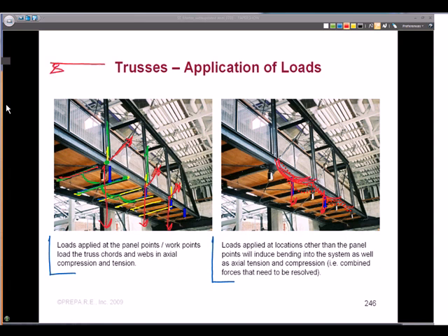Well, we could probably simplify it. It's just a point load in the middle. And the span, we could find that very quickly, right? M max from our loading diagrams equals PL over 4. Okay, now you'd have to calculate it, but that would be the approach. This is just a simply supported beam. It has continuity, but we could simplify it in practice and just put a point load on it as a simply supported beam and then design that for the maximum moment.